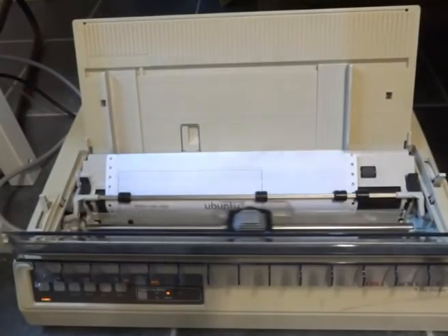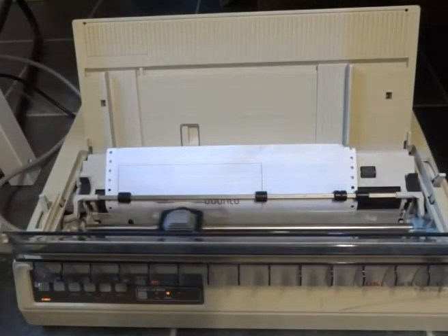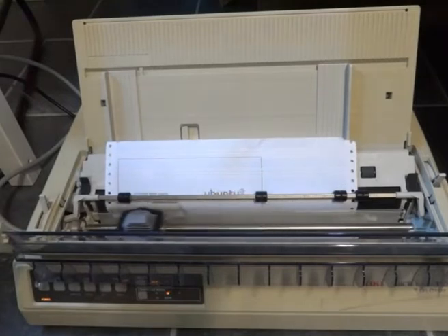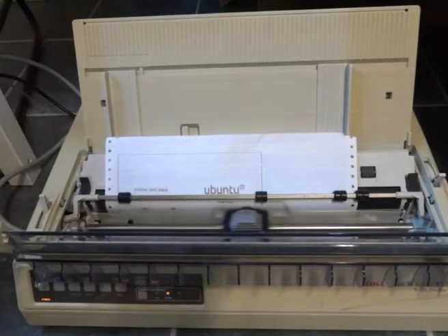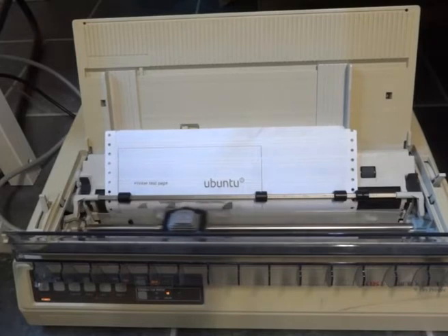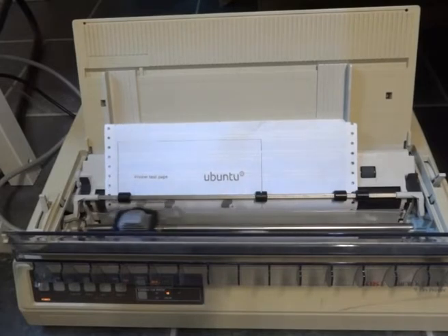So, whenever the PC would send data to the printer, it was actually sent to the very fast buffer memory inside the printer, and thus the PC could fill it at an extremely fast rate. The printer memory was so designed that it could accept the data from the PC at a fast rate, but send data to the print mechanism at a standard slow rate. So, the buffer was emptied at a slow rate.